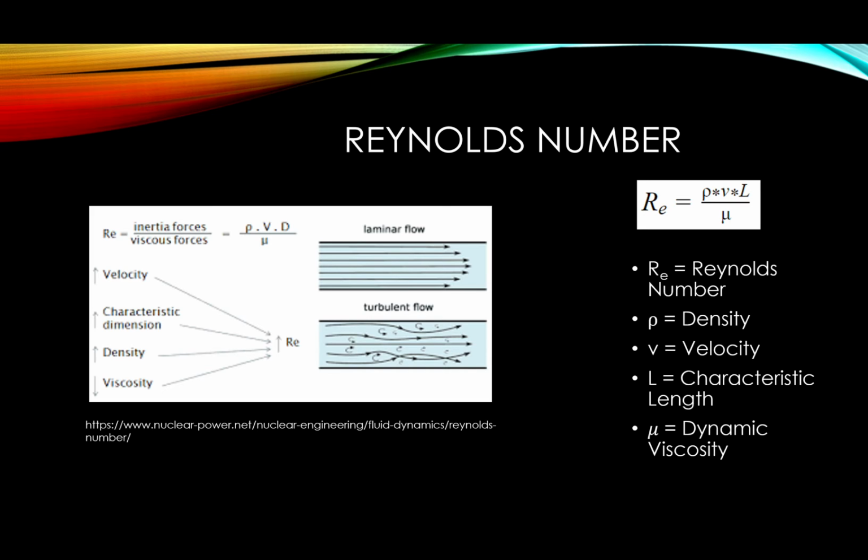The Reynolds number that accompanies a set of data can be used to apply the information gained from that test to other situations with a similar Reynolds number, like larger scale models or different atmospheric conditions during another test. Even running the same test at the same speed at the beginning and end of an hour can result in a different Reynolds number between the tests, making it difficult to apply both of these data points to another situation. The pressure and temperature at the beginning of a test run can change the density and viscosity of a fluid, therefore changing the Reynolds number for that test run. To home in on the preferred Reynolds number for each test, the speed of the wind tunnel would need to be adjusted. Running all of the trials at the same Reynolds number rather than the same speed allows all of the data to be compared and used at a different scale together rather than needing to adjust for the change in Reynolds number between each trial.